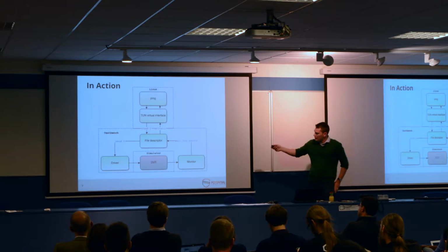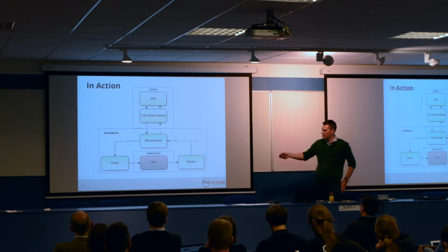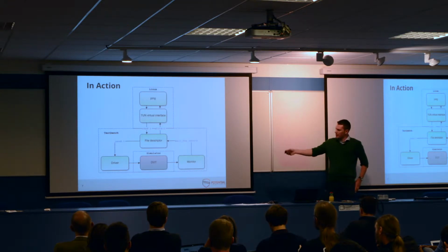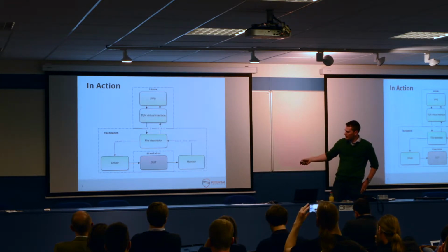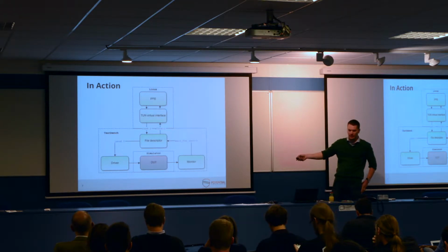So to do that, we need to create a virtual interface in Linux, and that's going to give us a file descriptor we can use in our simulation. We hook up our drivers and our monitors to the design, and then we receive packets from our file descriptor and send them into the design.